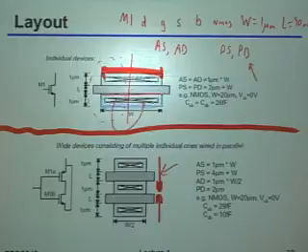Now, by the way, the other reason we just talked about for doing this is that if you do things this way, at least on one of the two junctions, you'll have a lower parasitic cap than you otherwise would have had because of this geometric sharing effect. Does this make sense to everybody?